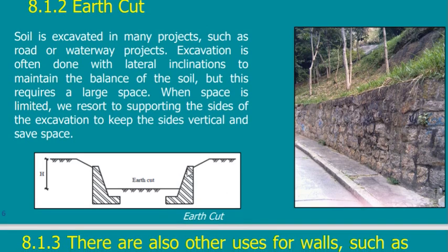any other, if I want to construct this retaining wall, how can I construct this one in this photo, how can I construct this wall to retain the soil behind it? How am I going to keep the soil in place while constructing the wall? Have you ever thought of this? The function of this retaining wall is to retain the soil behind it. But the soil is now there. How will it stand till I finish my retaining wall? In this case, I will need a shoring system.